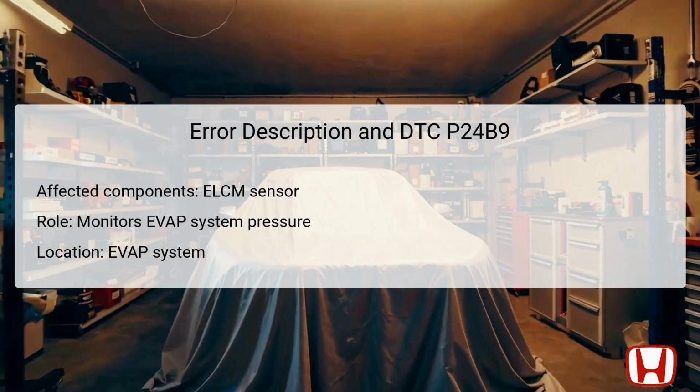The DTC P24B9 primarily affects the Evaporative Leak Check Module, ELCM, pressure sensor, a critical component responsible for monitoring the pressure within the EVAP system. Its role is to ensure that the pressure level remains within a specified range, which is essential for effective emissions control. Located within the broader EVAP system, the ELCM sensor is strategically positioned to assess any leaks or abnormalities in pressure that might indicate a leak in the fuel system.